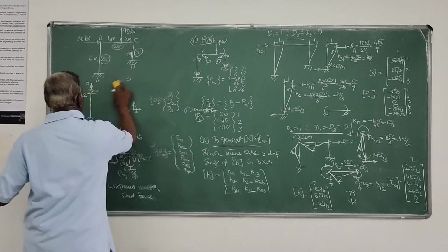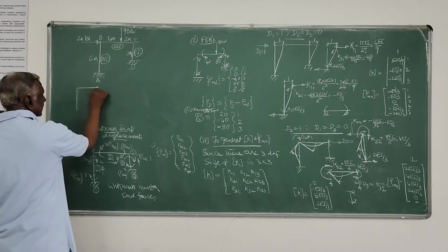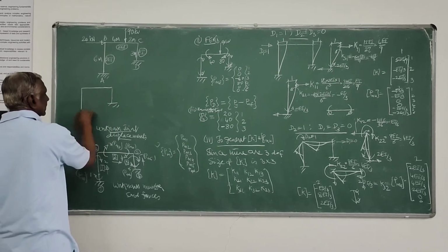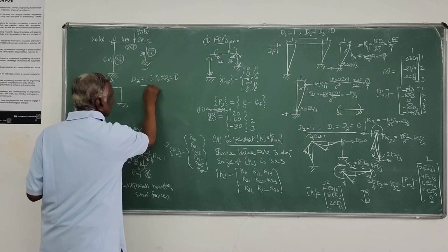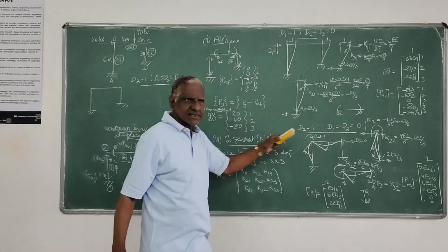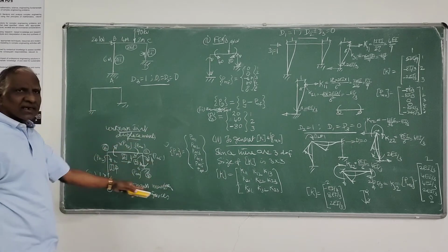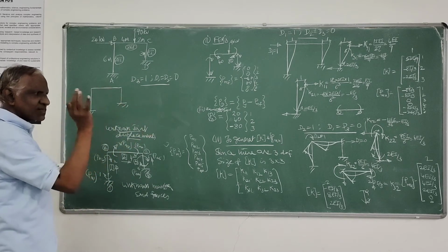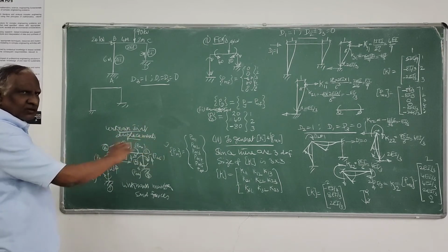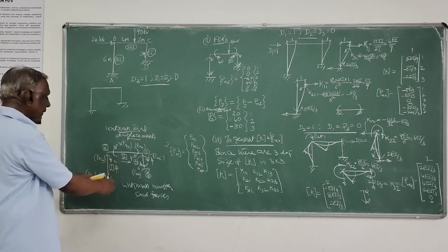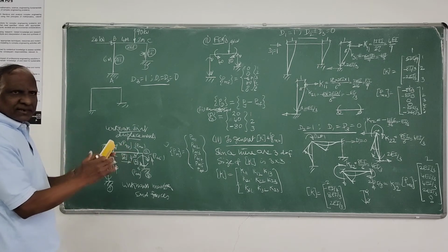Then you give the last one, you have to apply unit displacement in the direction of the coordinate 3. That is D3 equals 1 and D1 and D2 you have to keep 0. First case, second case, third case. This exercise you have to do because that is the major part of this computation, nothing other than that. K matrix, PMU. Then only you have to use that equation, where P is PD equals KD to find D, and this PM is nothing but PMF plus PMUD. So that's all. The other parts are only matrix additions.